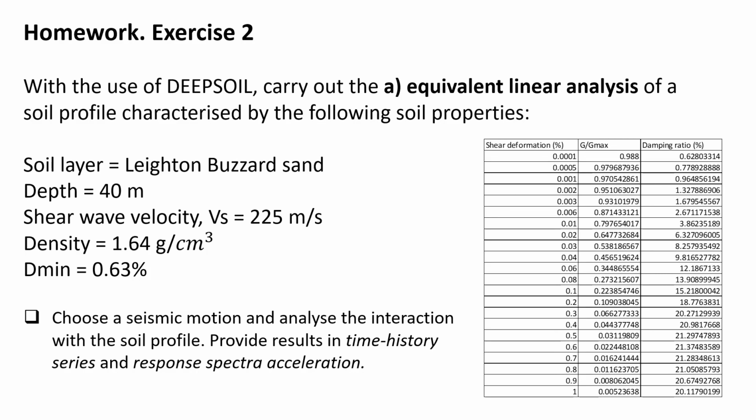Provide results in time history series and response spectral acceleration. That's what I want you to do, to compare the final results observed at the soil surface with respect to the values of the input motion at the top of the bedrock.